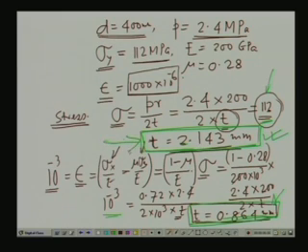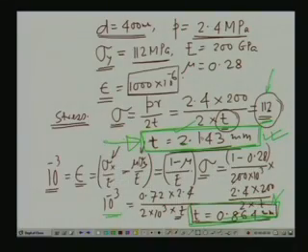So, this is the thickness of the vessel that is to be adopted, so that it satisfies both the criteria of stress as well as strain. The maximum value of the stress requirement is 112 MPa, and the maximum value of the strain requirement is 10 to the power minus 3. These two can be satisfied if we use the higher of the two thicknesses, which is 2.143 millimeter.